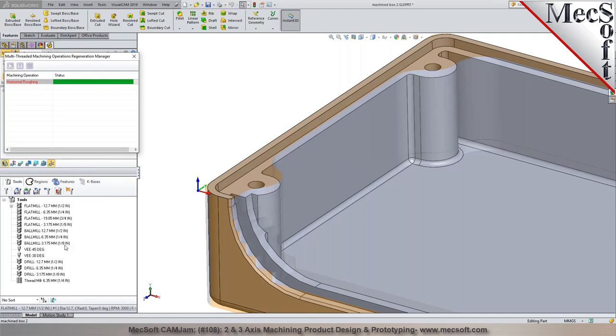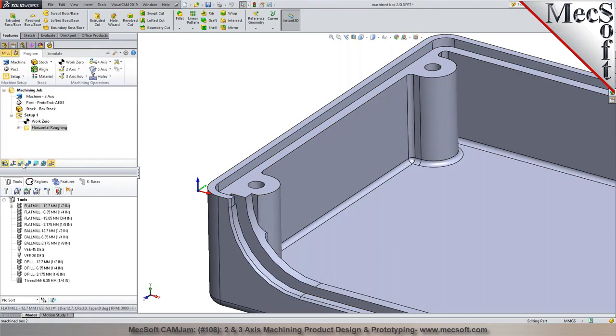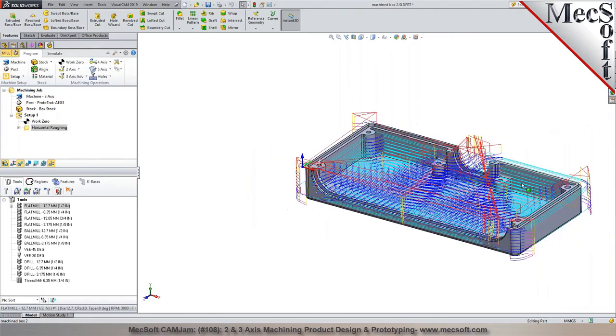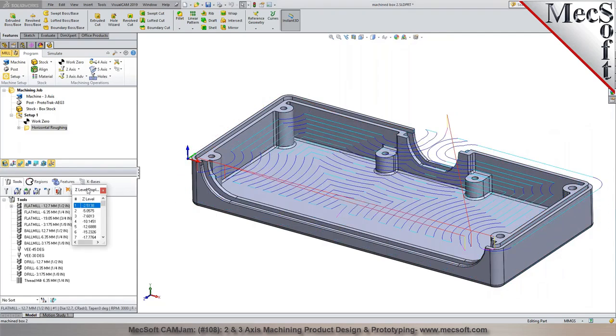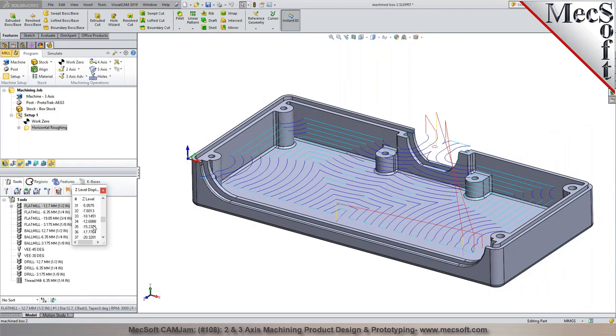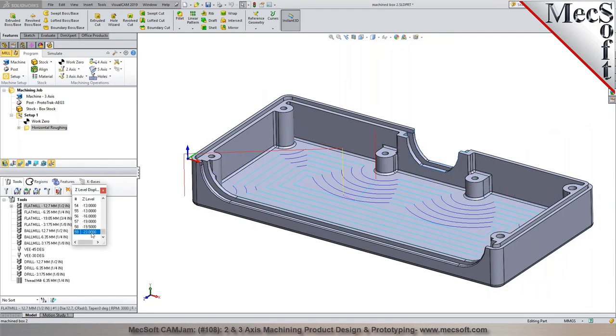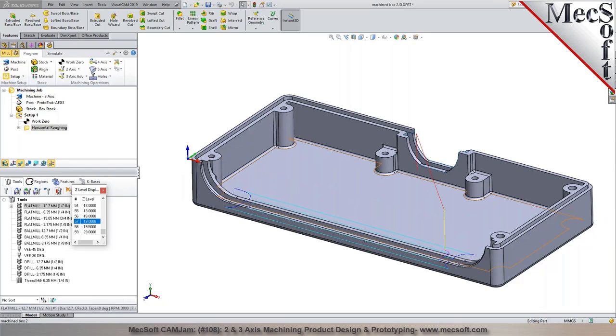Okay, now will that apply to all the flats like that? All the flats on these over here, it'll do the flat over here. Okay. Yeah, all the flats. If you take a look at the toolpath in here, as you step it down, you'll see it goes and cleans up each of the flats down at the floor right there. Okay, yeah, I got like five. There's like 5 flat levels on here. Yep. So it automatically takes care of each of the flats as well.